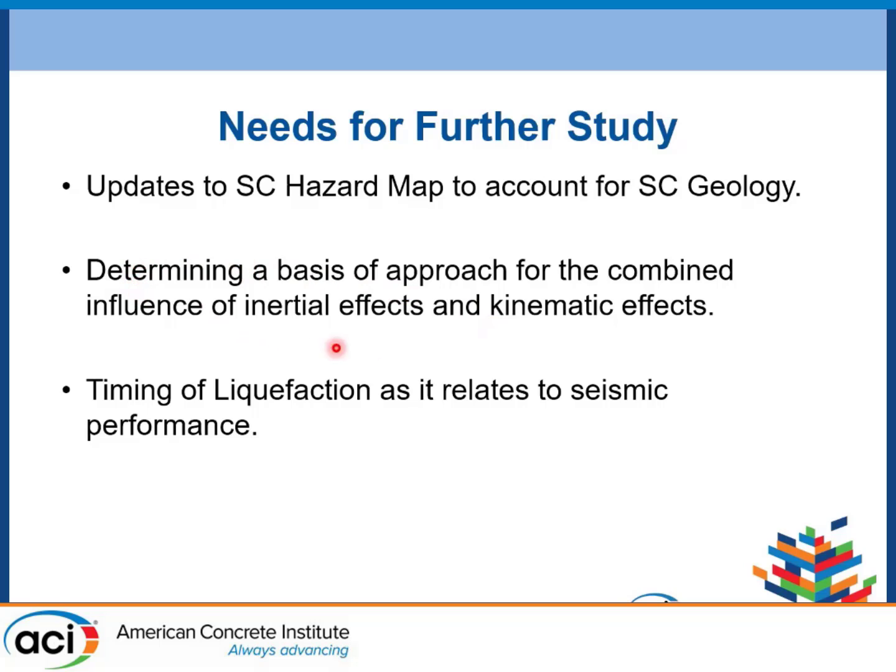One thing I'm working with right now on a bridge that I'm designing this week is the combination of both inertial and kinematic effects in liquefaction. So, for instance, if I have a bridge where the abutment is going to experience liquefaction in a seismic event, the slope failure of that abutment could be restrained by the abutment itself. We can use the substructure elements to help restrain some of those effects.